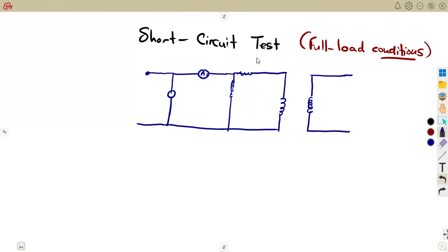As we considered part of the short circuit, we are going to need the current measured on our output there. So we're just going to consider this as our A2. All right, so this part, as I said, our wattmeter as we had before, our voltmeter here, and we're going to have this as our V short circuit.